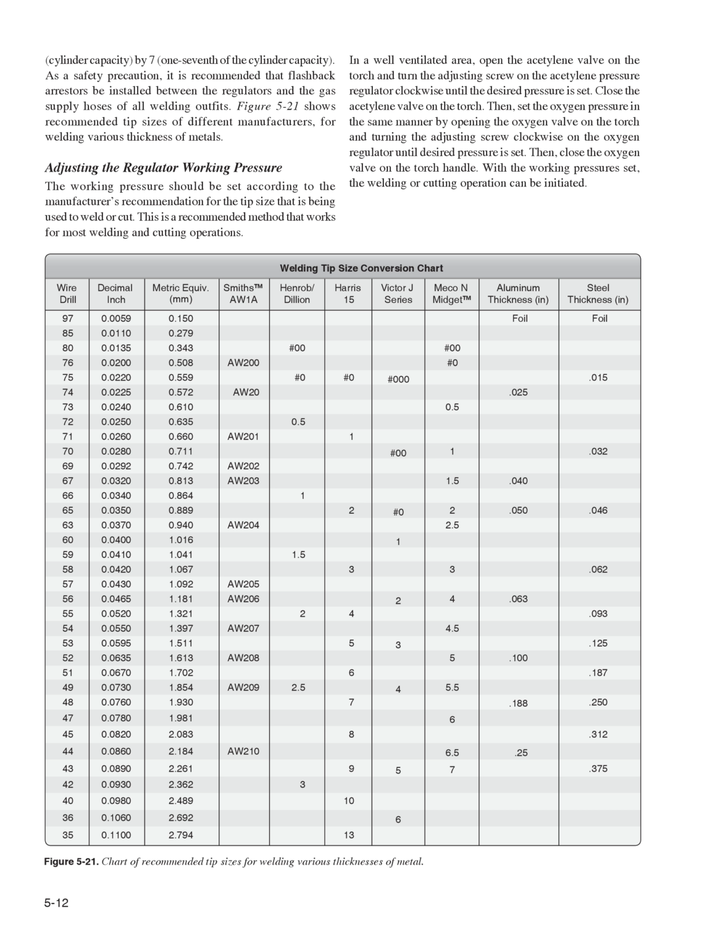The longer the feather, the more acetylene is in the mix. For most welding operations, the length of the feather should be about twice the length of the inner cone. The carburizing flame is best used for welding high-carbon steels, for hard facing, and for welding such non-ferrous alloys as aluminum, nickel, and Monel.